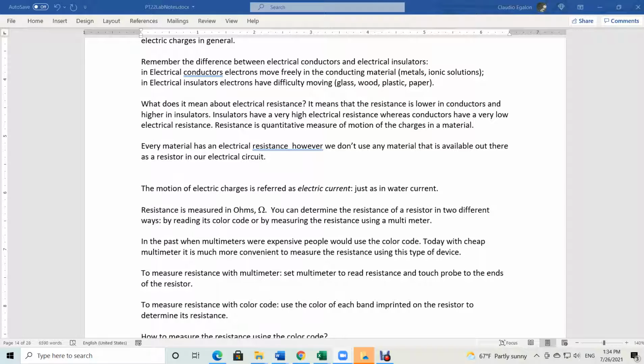20,000. See, I'm getting 9.8 thousand, 9,800 ohms for this single resistor, very close to 10,000. That's a 2% difference, which is, by the way, a big difference. Let's see this other one. 9,730. Okay, that's how you measure those things in real life.